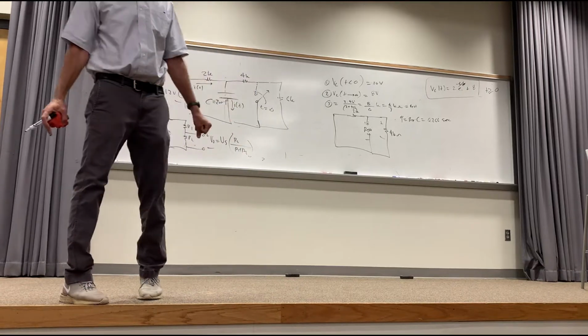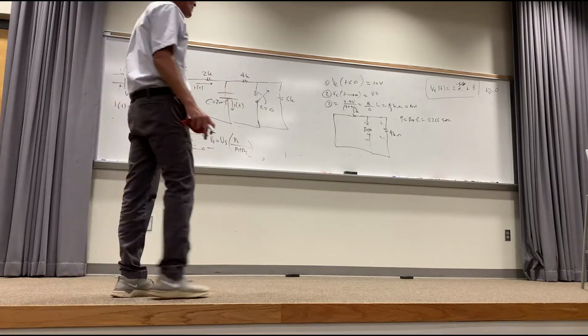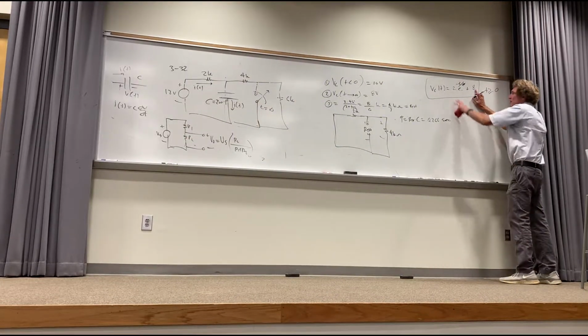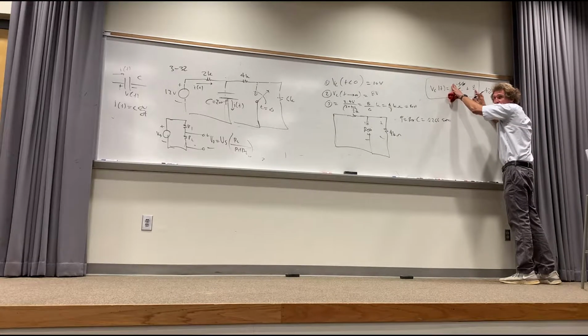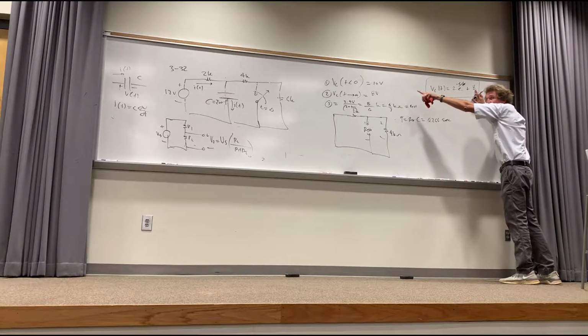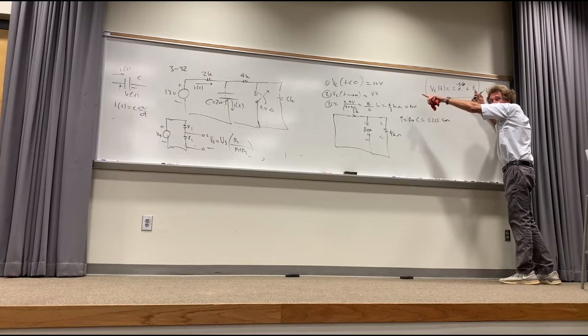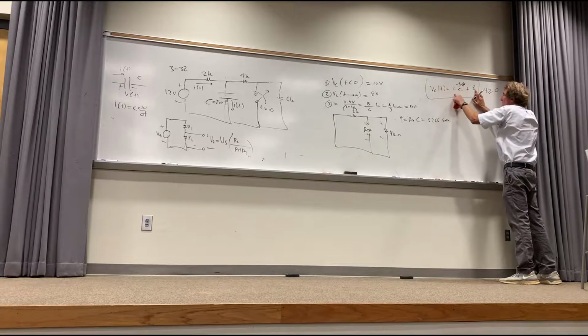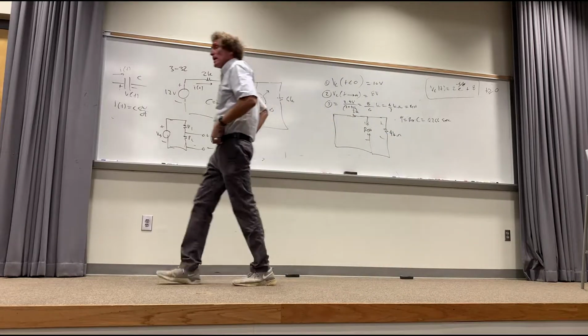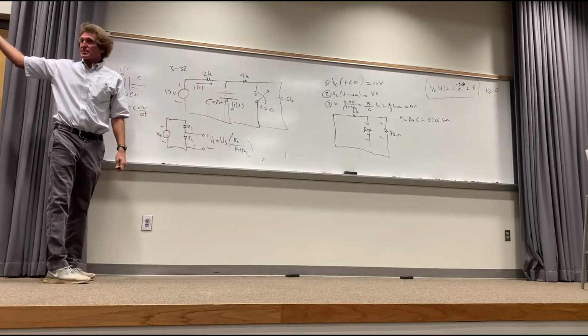Could you show how you got K1 again? First, we got K2 first. Once we got K2, we have 8, right? And that's K1. So K2 came from t equals infinity. The other point was at t equals 0, right? At t equals 0, we had this. At less than 0 or 0, it's 10, isn't it? Right there, do y'all see it? Can you see it up there? It's 10. 10 equals K1 plus 8, so K1 is 2. That's how. Next question from the audience.